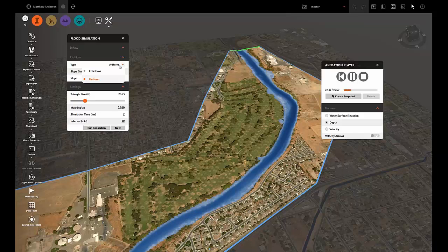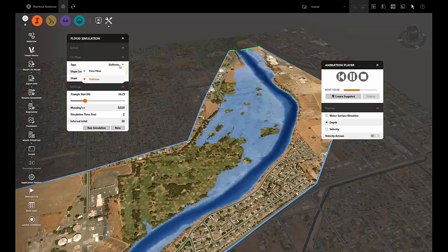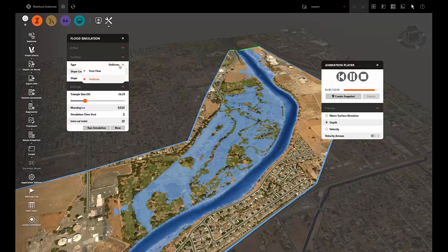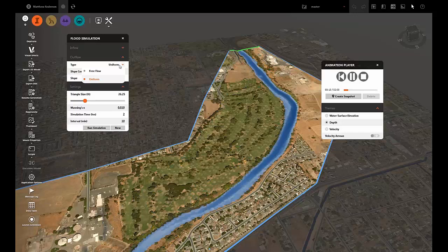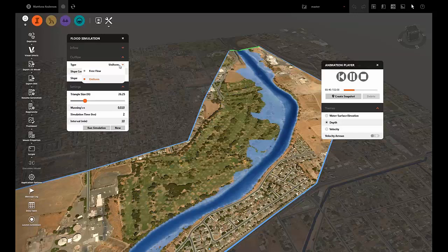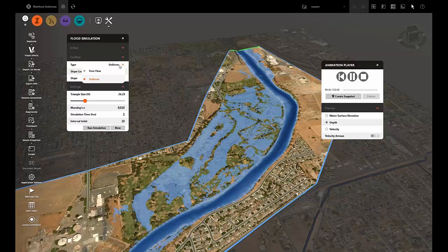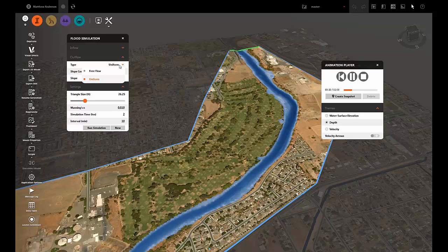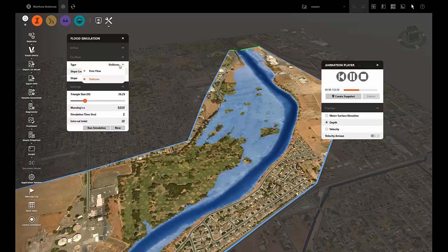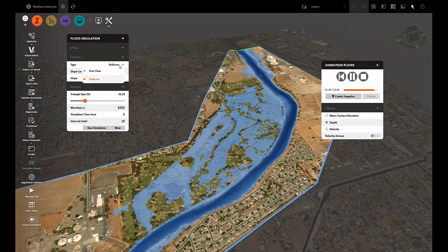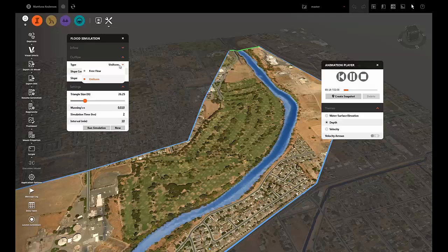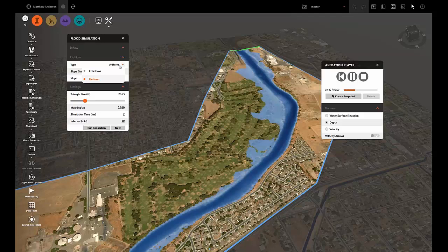But they have their way. They both are commonly used in practical applications. Sometimes, especially when you have multiple outflow boundaries, you can use free flow. Sometimes it's more convenient because you don't know anything about that boundary. For example, you don't know the slope. You are not very sure about the cross-section there, so you can use free flow as an initial approximation there. If you have more data, then you have slope and other information, then you can use the uniform flow condition.